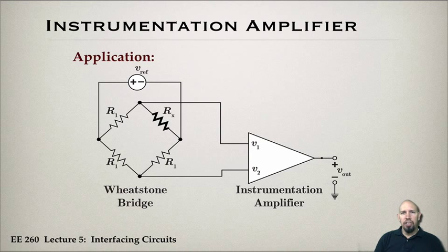If all the resistors are identical, that is if Rx is equal to the other resistance values, then this bridge is in balance. Notice that we have a reference voltage being supplied across over here, and if this resistance is the same as all the others, then the resistance along this path is equal to the resistance along this path.